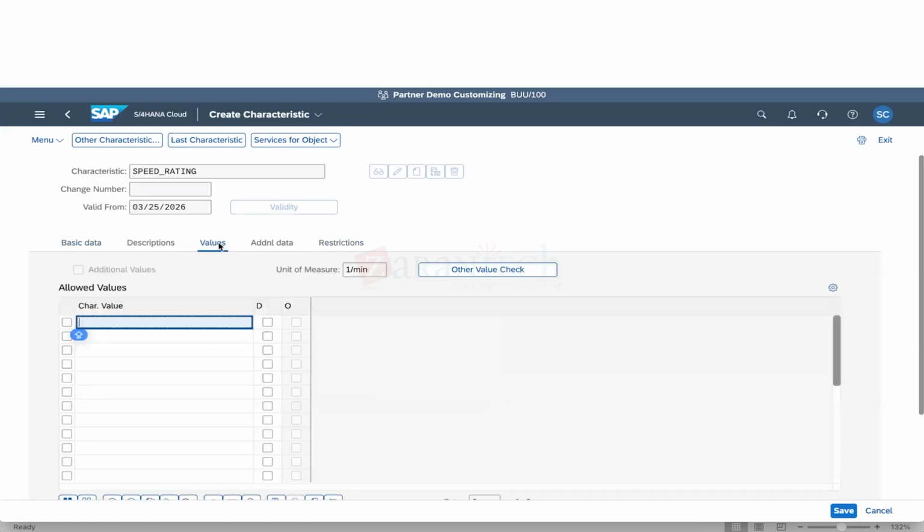I know what the minimum speed and the maximum speed of the motor is. It cannot go beyond that particular range. So I'll give 0 to maybe some 3000 rotations per minute. My value should be between this for any motor considered. It can't be more than that. If you are aware of the technical specifications, based on that we can provide this. So I have set this range.